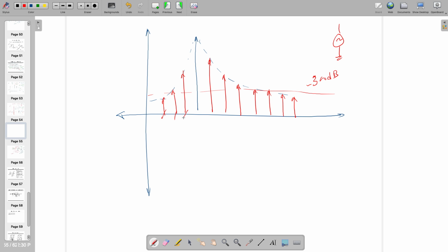By the way, each point is known as a bin, and this whole process is known as binning, right? So when you are doing these things, if you are seeing such kind of things, you can declare that as the Eiffel Tower effect, okay? Because it looks like the Eiffel Tower. We don't call someone that your FFT or DFT is wrong. We are going to call it your FFT is leaky, right? These are the technical words I'm talking about. So your FFT is leaky, and we don't want to see any leaky FFT.